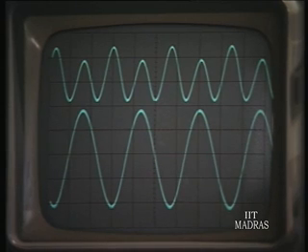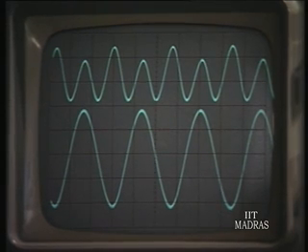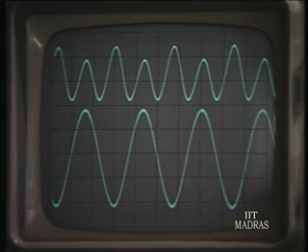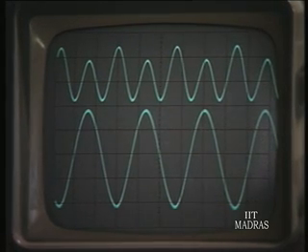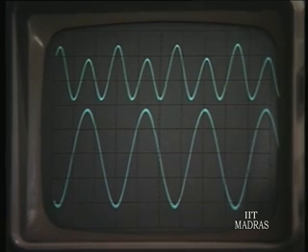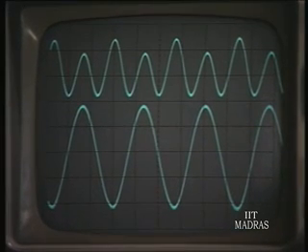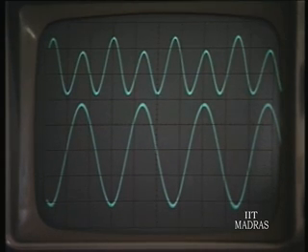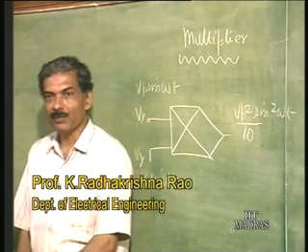So, the feed through component also is coming along with the doubled frequency component. This can be eliminated by adjusting the DC applied to one of the inputs, so that the feed through component gets cancelled. So, this gives you a frequency doubling effect, and we can multiply frequency by using successive multipliers, and we can generate a periodic waveform this way.